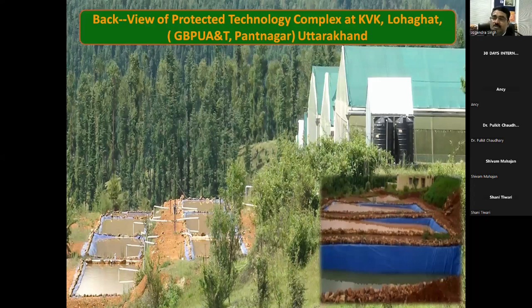We can use rainfed cultivation, but in protected, covered cultivation, no rain enters inside the polyhouse. So how can we grow crops without water? So we have developed a poly tank for roof rainwater harvesting. We make the poly tank and link it to the roof rainwater harvesting, and then the water will be used for the irrigation system through the filter system.